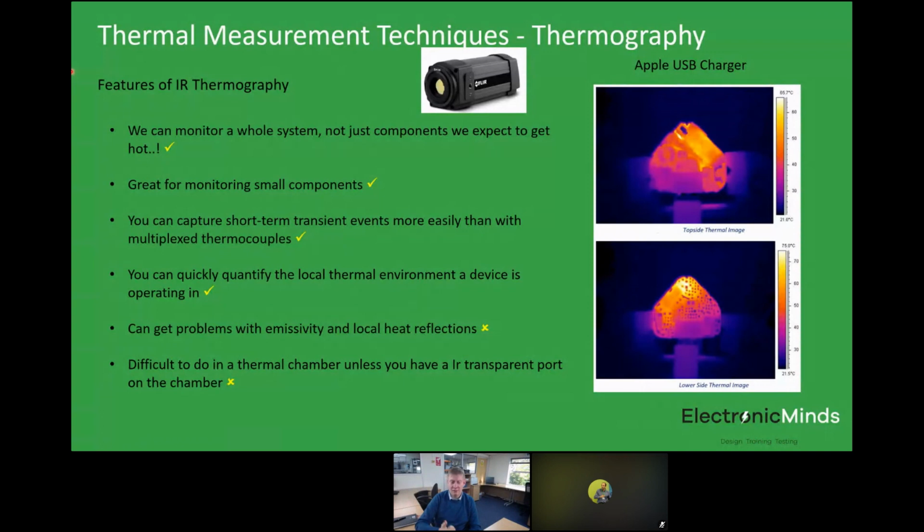The other side of it is you also want a liquid that has a high thermal capacity. So you want to be able to put a fair amount of energy into it without causing the temperature to rise. And there are some other things, like the level of contaminants you get in there, and how often you then have to change the liquid coolant. I think I remember reading about effects whereby, if your coolant is subjected to electric fields, it can create problems as well. But I'm guessing a little bit on that. It's a very complex science, I think, to choose that particular liquid cooling system, and it's really determined by the application.